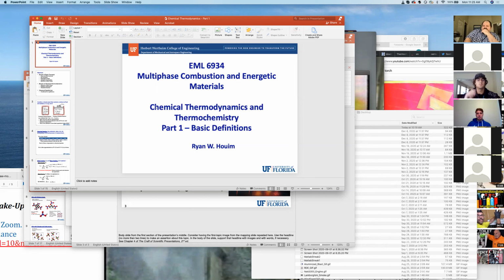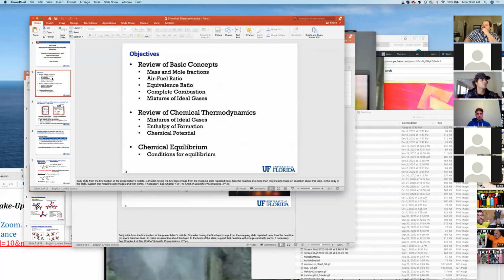So this here is part one. Here we're going to start the review, and we'll start with the thermochemistry. Part one will just be the basic definitions, and so we're going to review what mass and mole fractions are. We've got to start at the beginning: air-fuel ratio, equivalence ratio, complete combustion. Basically, what is meant by that? Mixtures of ideal gases, and we'll be extending this to mixtures of real gases because that's becoming important in modern combustion theory.